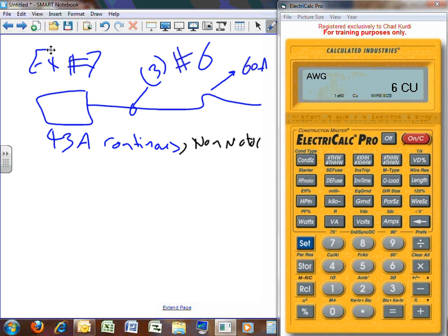Before I do anything, Phil, I want you to look at this. And if you guys want to understand this one, you have to listen to what I'm going to say right now. Whatever the derating gives you, you shall not end up with a conductor less than number 6. Did you guys hear me?